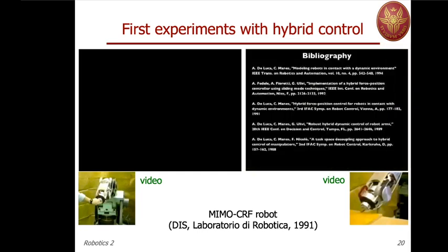Now, there's one consideration to be made here. These are the reference papers that you can access very easily in Xplore. So the main issue here is, indeed, when there's a jump in the environment, or if there's a variation of orientation, the filtering effect of the hybrid force velocity control just neglects the components which are measured, in fact, by the force sensor, which are not only normal to the surface. I mean, they are normal to the surface, but not to the expected one.